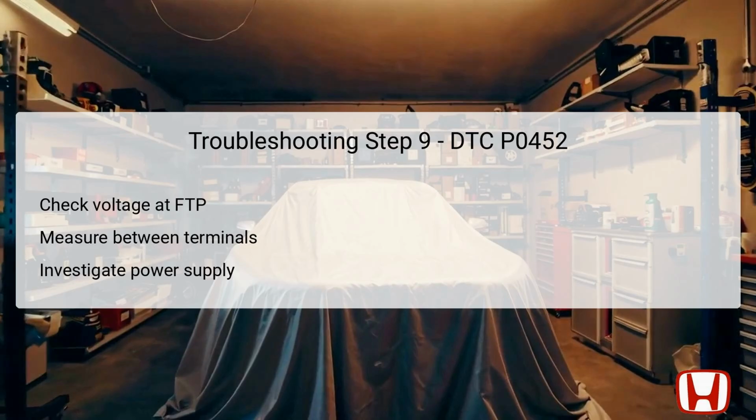If this reading meets such specifications, it suggests that the sensor might still be operative. However, if the voltage is inadequate, this could potentially reveal a deeper issue, either with the sensor itself or the wiring harness leading to it. This step is crucial to narrow down the malfunctioning component.